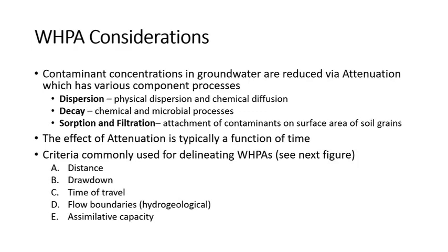And then you also have the decay, and these are the chemical and microbial processes which transform or consume the contaminant. And lastly, we also have sorption and filtration. These processes involve the attachment of contaminants on the surface area of your soil grains.